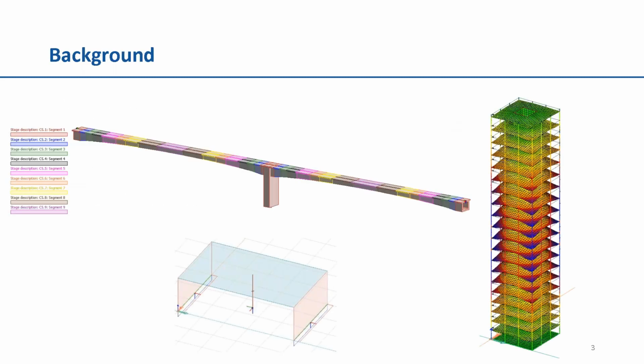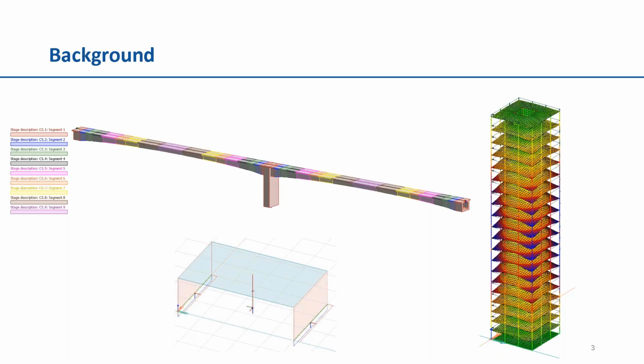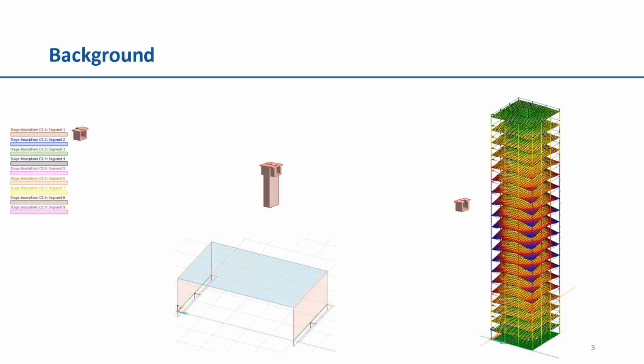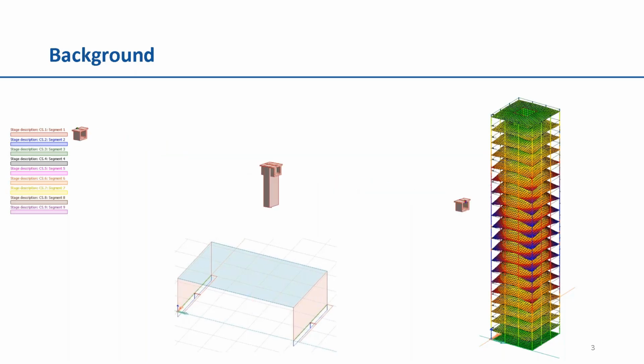The construction stage feature is an analysis which will take into consideration the different steps of the building sequence. The sequence can influence deformations, load distribution, stability, and so on. For example, a bridge may experience the largest forces during or just after the construction sequence is finished, or a high-rise building where the deformation during the construction must be taken into consideration to obtain a correct load distribution, or an existing structure that maybe needs reinforcement.